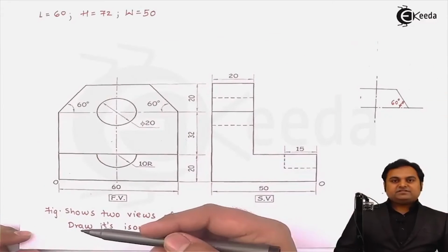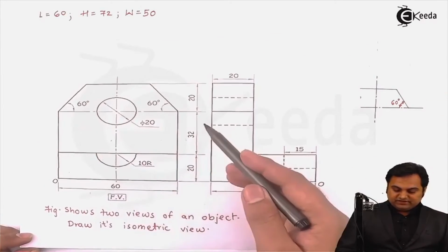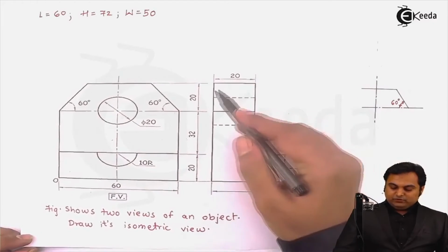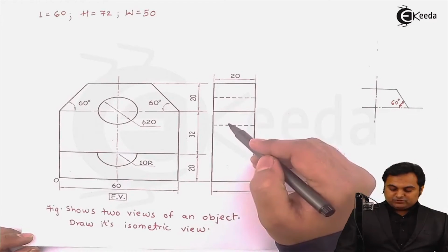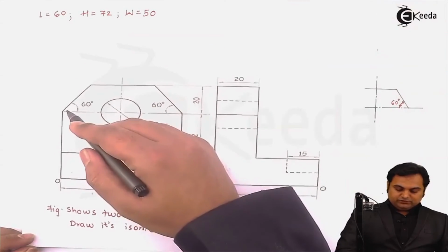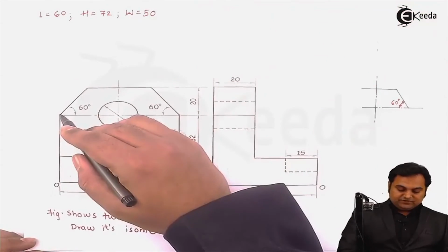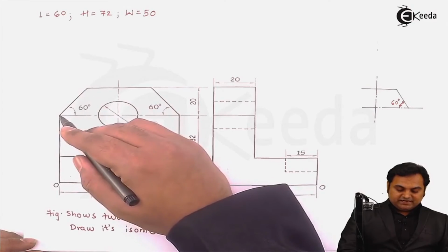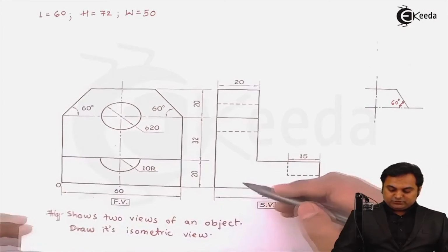if we see this diagram here also, as the surfaces are inclined and in the side view there is a dark line between these two surfaces that indicates change of plane. So when I look into the front, I can say that the surface which is at the top, that is inclined, and the bottom surface is straight, which is vertical.